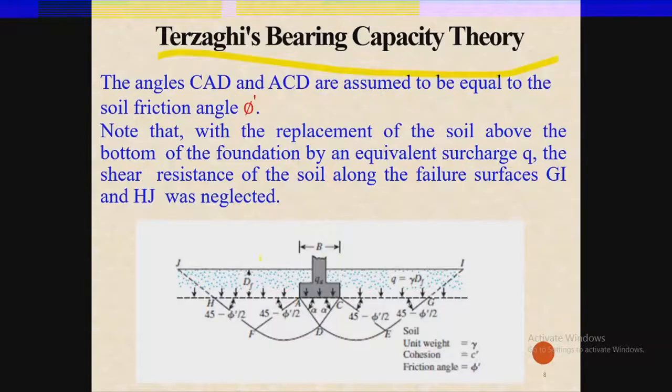This picture is basically the representation of the failure mechanism which was assumed by Terzaghi, and it is just similar to the failure mechanism of the general shear failure.